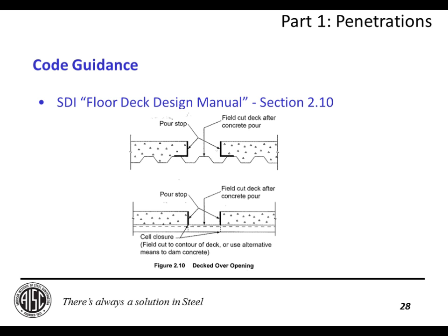SDI is a little more clear in that they require in their floor deck design manual that you put in a pour stop, you place the concrete, it then achieves 75% of its design strength, and at that point in time you field cut the deck after the concrete pour. You don't cut it ahead of time. And that's simply because the deck wasn't designed to have a hole in it for the wet weight of concrete. So you want to go ahead and use all the strength of the deck that you can for the resistance of the wet weight of concrete, and then come back and cut out your opening at a later time.